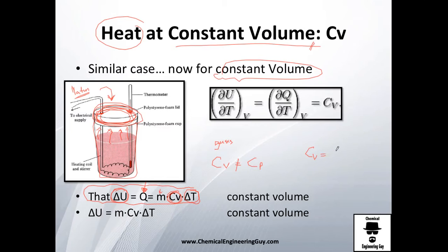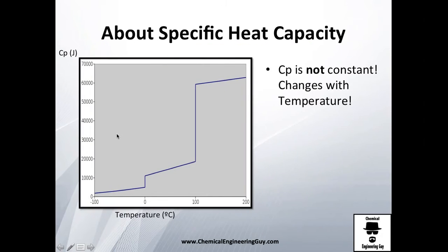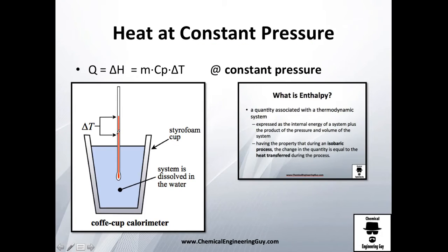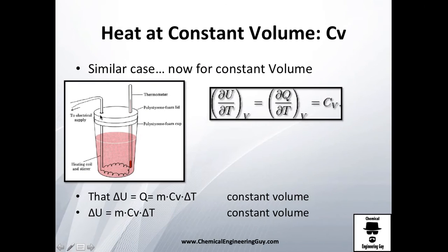As a general rule, CP and CV for solids and liquids, it's okay to take them as equal, but for gases, no. And it makes a lot of sense because here the same gas is going to be increasing the pressure, whereas in the other case, if you evaporate something, well, it's going to go out and the pressure is going to remain the same. So this is constant pressure. This will be constant volume, but not constant pressure. So that's why you're going to have differences in the specific heat at constant volume and constant pressure.